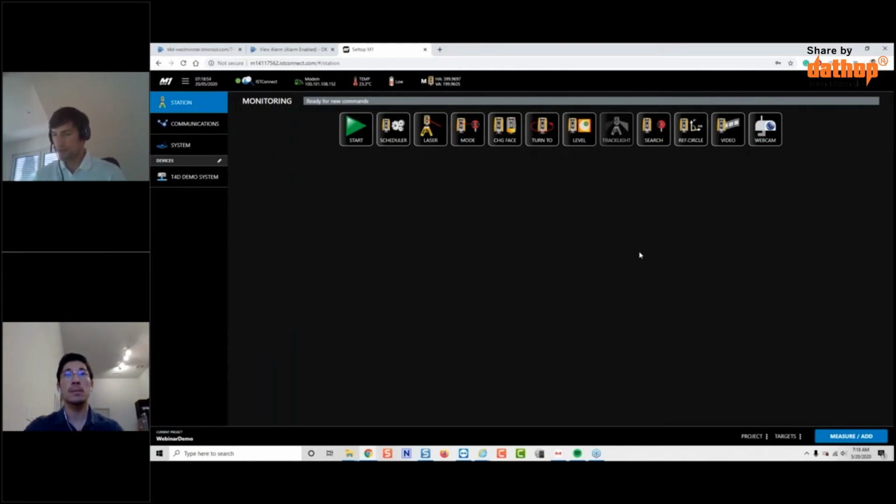A very similar question, maybe a combination of the previous two questions: is it possible to link T4D to a network of GNSS receivers to study the displacements of a city in 3D? It's a question from Youssef. So yes, it's pretty similar to what I've just described with total stations.